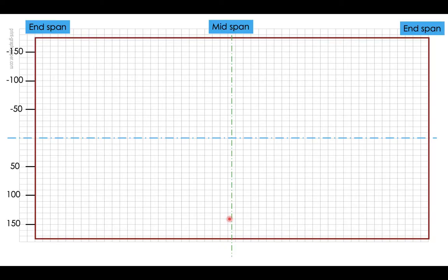And after we have already determined all the ranges of eccentricities, using the values, we can actually plot the tendon profile, which will show us the cable zone limits. So you can see here, this is one curve that we can draw based on equation 21. So we have the point here that is for the end span. So this is for the 2 points.